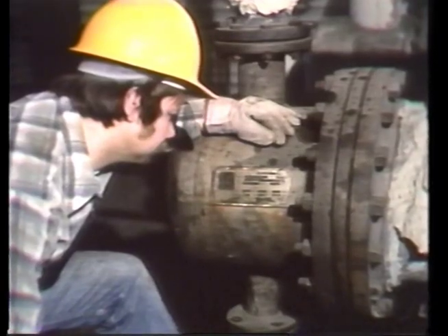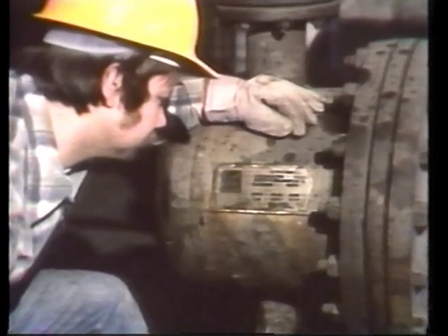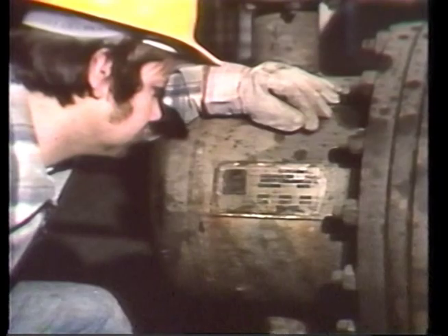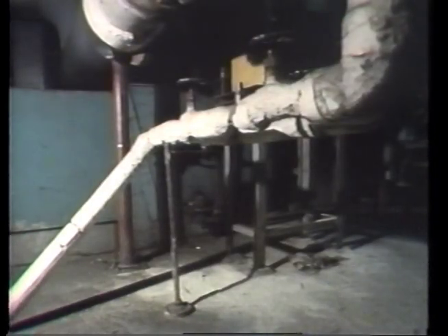This is sometimes referred to as a trapping problem rather than a trap problem. Well, what do you look for when trying to see if the trapping system is working properly? Well, here are some checks that experienced mechanics routinely perform. Make sure the steam pressure at the inlet to a piece of equipment matches the nameplate data on that equipment. Check to see that the drip lines are connected to the lowest point in the system. Check to be sure the drip line is sloped down toward the trap and that there are no dips or pockets that would slow the flow of condensate.